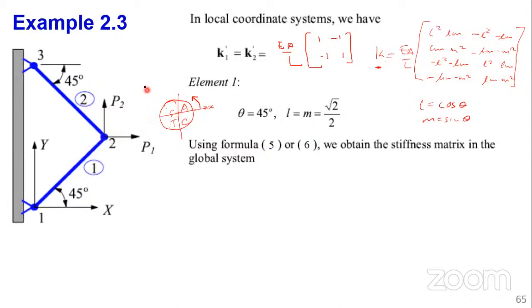Now, number 2, we measure our angles from node I. We read node I to node J, where I is less than J. I is the smaller node. So if you're talking of an element with nodes 1, 2, or with nodes 5, 6, you can't start reading your angle from node 6 coming to 5.